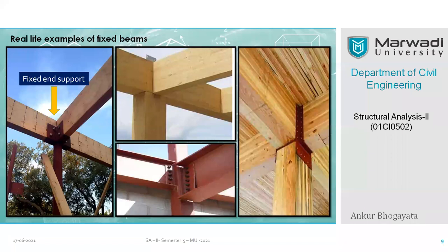When you do that, you are actually offering a fixed joint to the lintel, because lintels are responsible for the long protrusion or long extension of the concrete chaja, right? There is a plate-like RCC structure which protects your window, and sometimes bears forces, and is many times utilized as an elevational decorative part also. So in that case, you are offering a fixed joint indirectly.